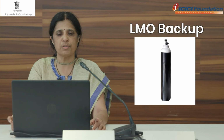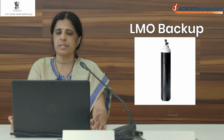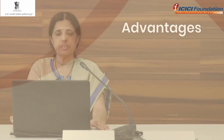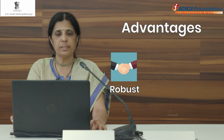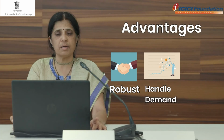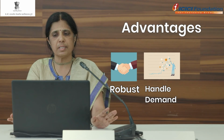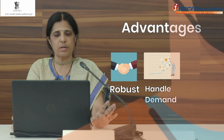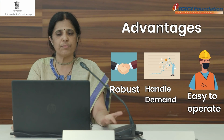Coming to backup, the primary source could be LMO, the secondary could also be LMO, and the tertiary could be a jumbo cylinder bank. The quaternary source could be a trolley-mounted individual jumbo cylinder by each ICU bed with 2-stage regulators and tubing attached. So what are the advantages of the LMO system? Why is it so popular? It is a very robust and the most reliable system currently available. It can handle unexpected increases in demand at hospital level relatively easily compared to any other system available in the market. Any person with basic educational qualifications, I would say 12th pass, can oversee the system if trained.